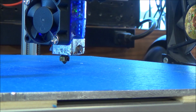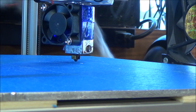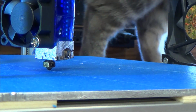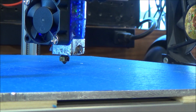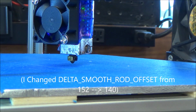Okay, so I'm going to go to the side a little bit. Notice that I'm fixing to crash into the bed because it's coming closer. Now it's almost crashing into the bed again. So it doesn't look like it's a level problem. It looks like it's a printer radius problem. So that definitely made it worse.